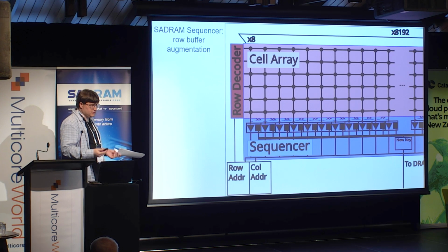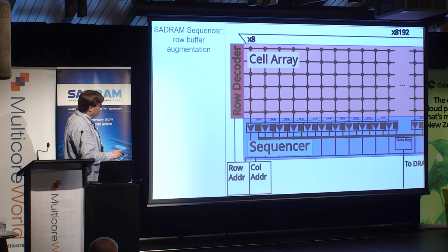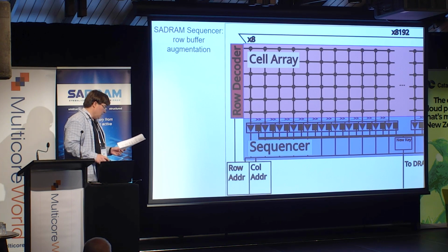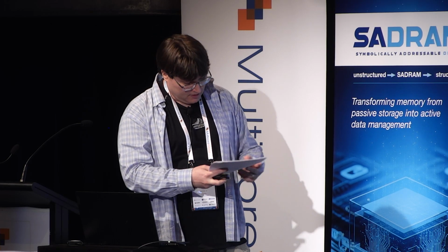We may not be able to do that if we have to make compromises for how much logic we can put down here. This is on the DRAM die, so it isn't cheap to put complex logic on it. If we can't have a simultaneous comparison, then we go with the binary search tree pattern, or we search through this with a binary chop.